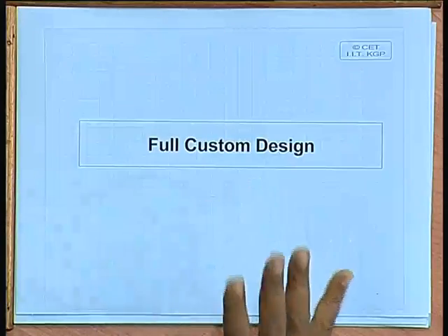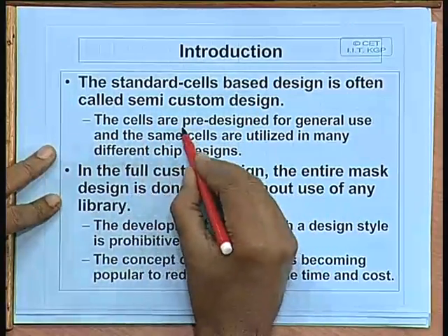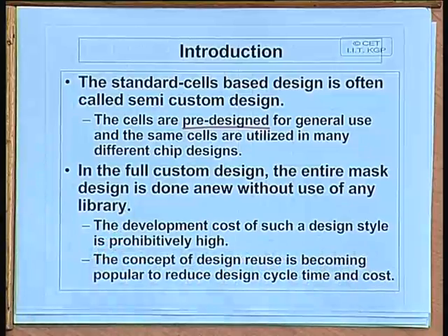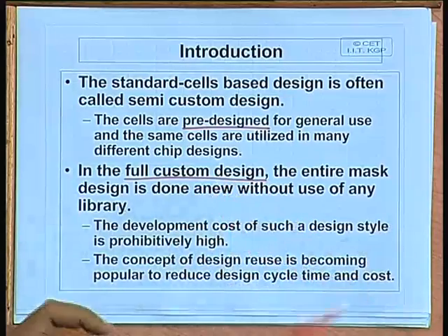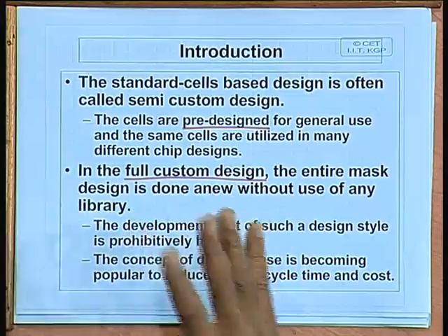And finally, a very brief look at full custom design. Full custom design, it is entirely up to user. There is nothing fixed or constraint which you have to follow. The standard cell design is based on cells which are pre-designed with some specific geometry. Well, in the full custom design, it is not necessarily that everything you have to design from the scratch, because today people seldom design everything from scratch. Something may be there in the library also, but they can come in all sorts of shapes and sizes. There is no restriction that they have to have the same height or anything.